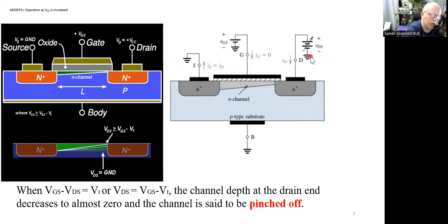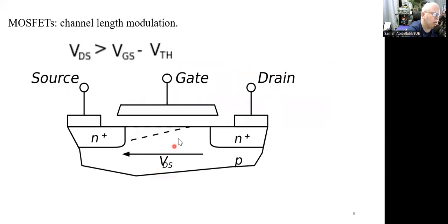If you increase the voltage greater than this VDS sat, the pinch-off point starts to move from the right to the left toward the source, and your current starts to be clipped because you generate a very high resistance region, or in terms of semiconductor, we can say you establish a depletion region here just before the drain. So your channel is no longer continuous, it has become somewhat discontinued by this pinch-off effect.